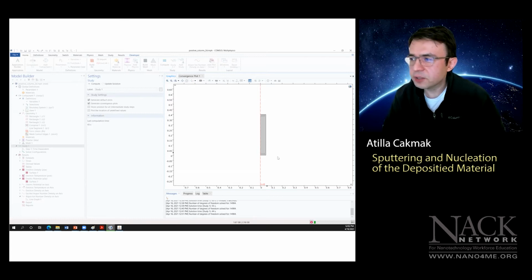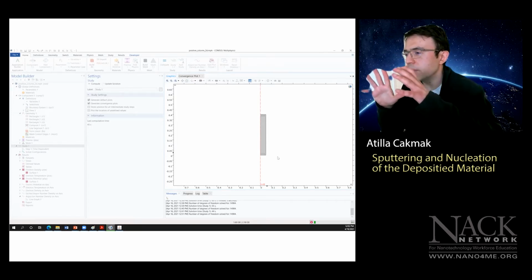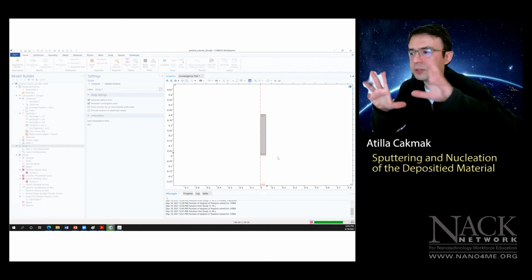Kendra says no, probably. And that's why I added this here for you to see. If you do not feed enough gas, there won't be enough argon particles to ionize, and there won't be enough electrons generated as well. So we may not have enough particles to work with, and we will fail. We won't be able to excite a self-sustainable plasma for these parameters, of course. I'm not generalizing this. I'm not saying that with 0.05 torr you cannot do that.